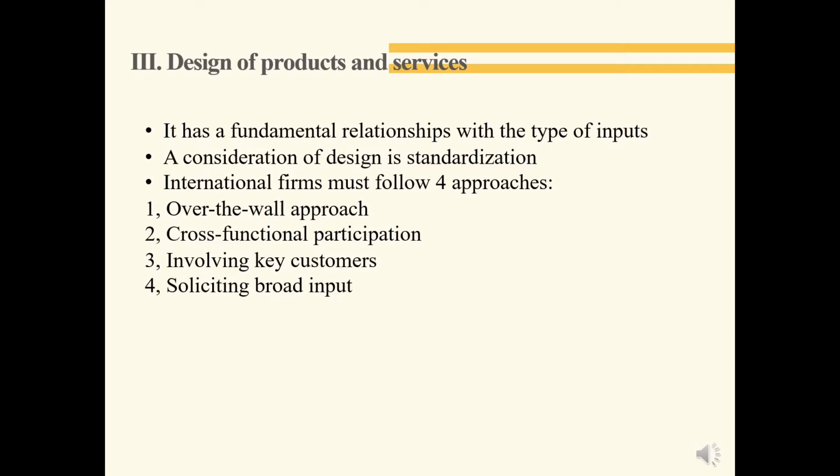And in order to consider standardization, any international firm must follow the form of approach here. The first one is the over-the-wall approach. It is a sequential approach to design where product designers design products and send them to the firm's manufacturing engineers, who check for problems, and then they can fix them if necessary.